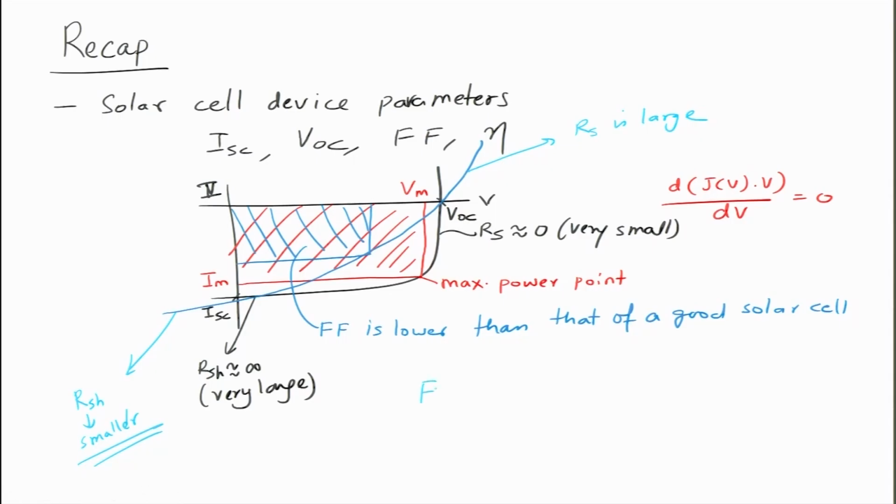So, the fill factor is basically, as we said, Vm Im divided by P in. This is the incident power, and you can write it in terms of energy or power. So, Vm Im is the extracted energy out of a solar cell, and this is the incident energy. So, if Vm Im goes down, this is efficiency, yes, you are right, this should be efficiency.